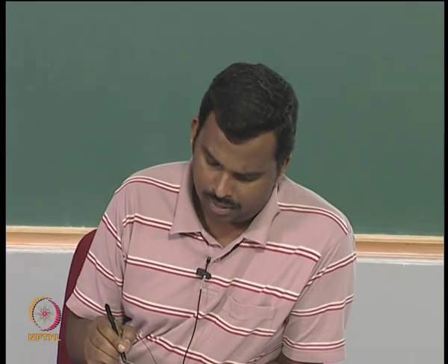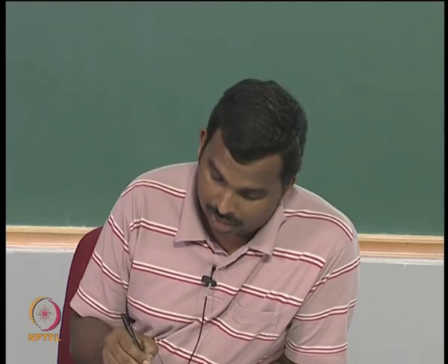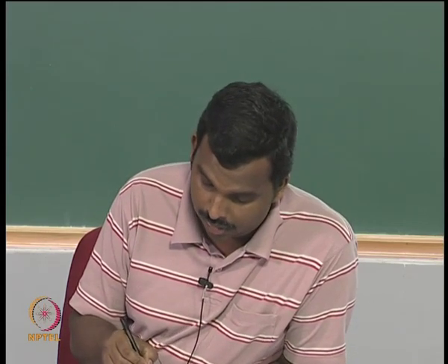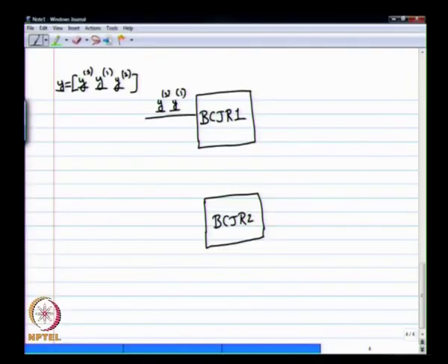So YS and Y1 is input to that, and it is going to put out an output. What will its output be? It will give me the LLRs for each of the message bits. Likewise, I can think of YS and Y2 going to the second BCJR decoder, and that will give me once again LLRs for all the systematic bits, for the same set of bits.